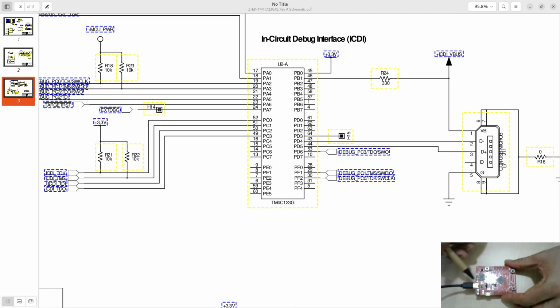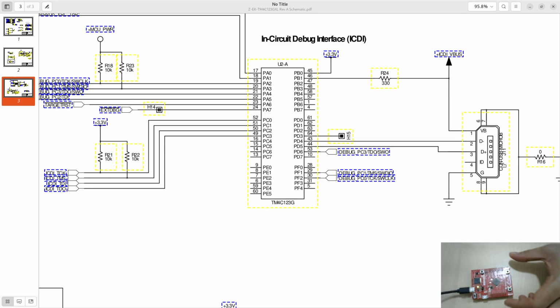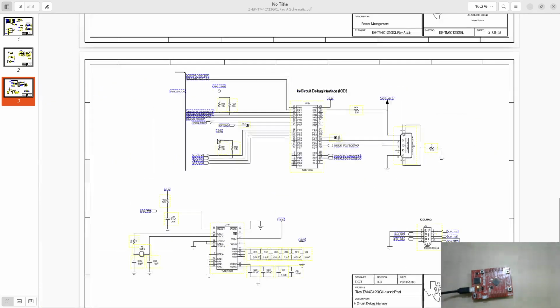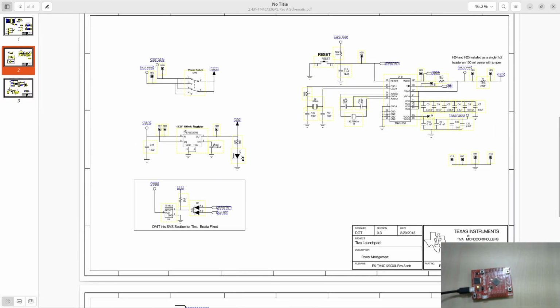So this is the chip that is basically talking over USB and acting as your interface between the computer and this particular chip. And this is the chip that is actually being used for whatever we are talking about. So this you can see is U1, the designator U1. I need to figure out where the LED is connected to this chip, so let's go and see where these LEDs are connected.